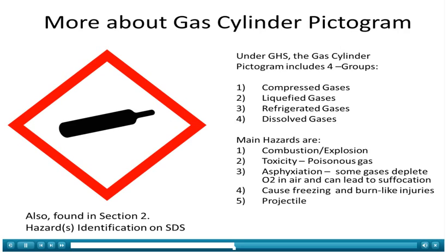Main hazards are combustion, explosion, toxicity, poisonous gas, asphyxiation. Some gases deplete O2 in air and can lead to suffocation, cause freezing and burn-like injuries. Projectile. Also found in Section 2, Hazard Identification on the SDS.